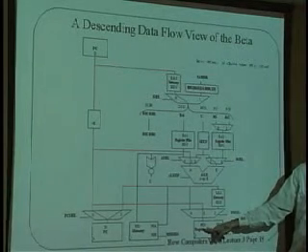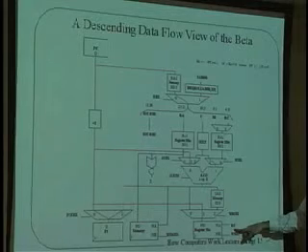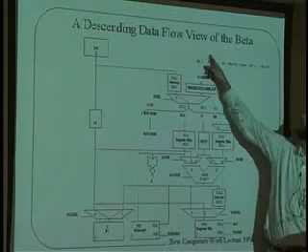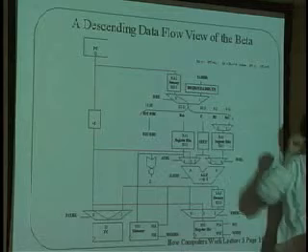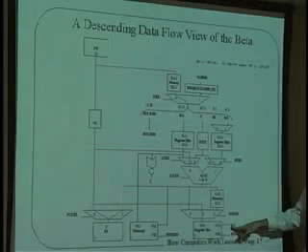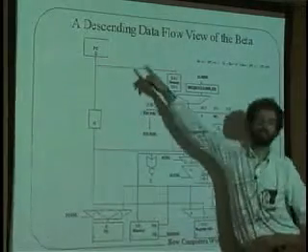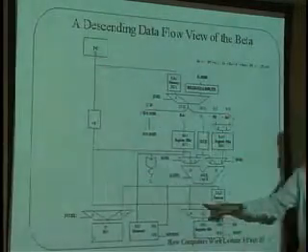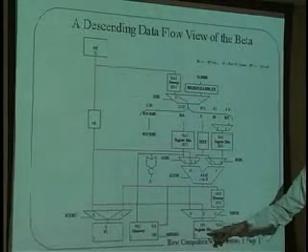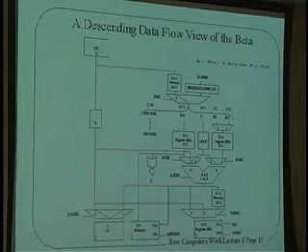Now, which register will get written? The one indicated by register C. And so this is the way that we implement the first part of this instruction, which is remember where I came from. RC gets loaded with the contents of the PC plus 1. And that's happening along this path right over here. PC plus 1 goes into the register file written as RC. Nice? On these diagrams, when lines cross, they're not...